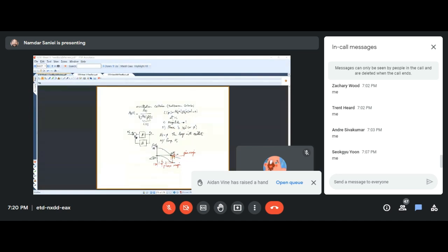So the gain margin is the difference that we have in the gain until it becomes 1. 1 means 0 dB. In dB, it is 0. So the difference that our gain has with the 0 dB, which is the horizontal axis, in magnitude, is referred to as gain margin.